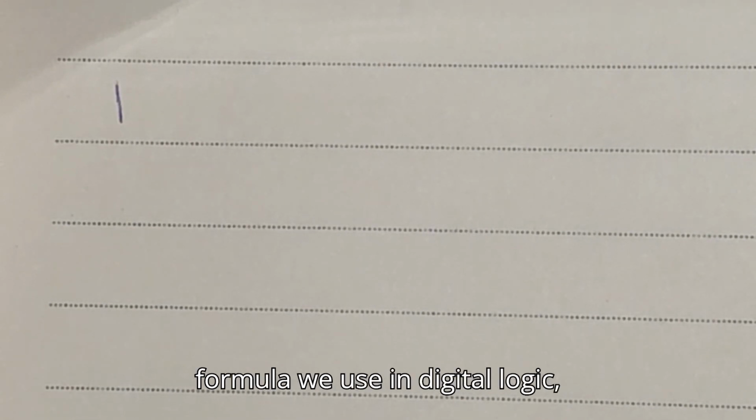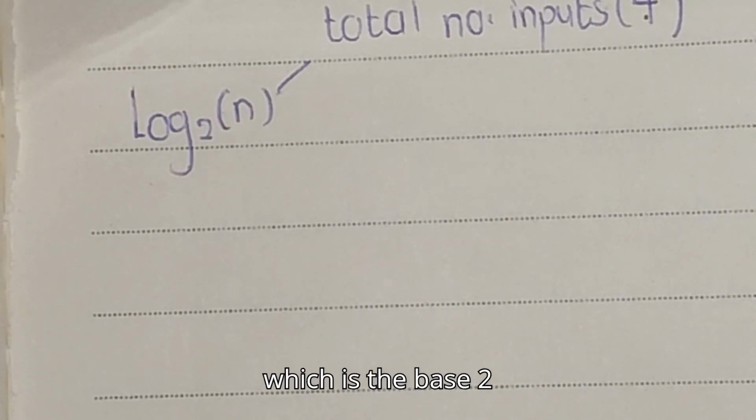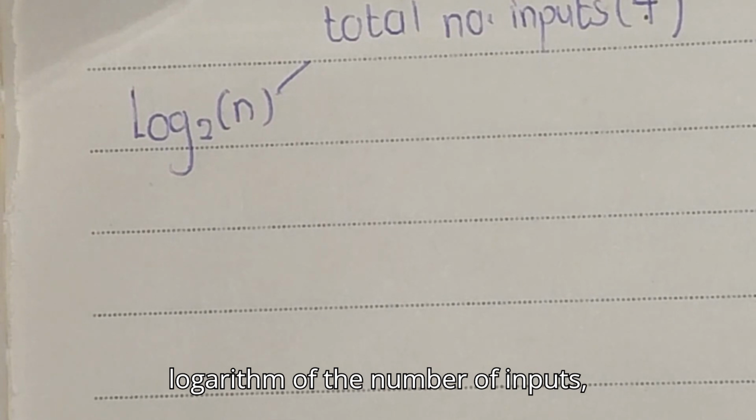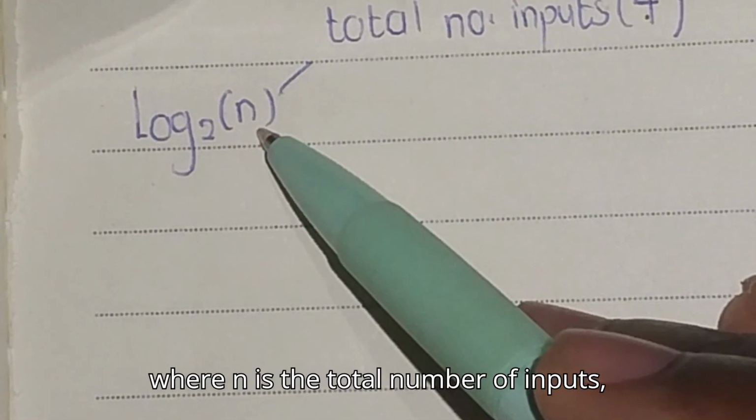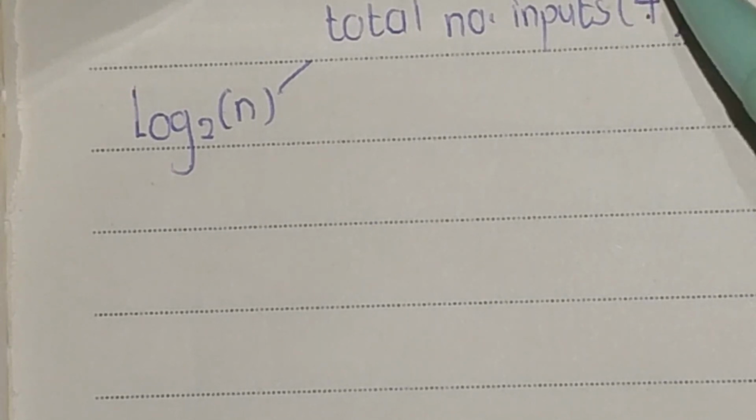To figure out how many select lines or control signals we need, there's a simple formula we use in digital logic, which is the base 2 logarithm of n, where n is the total number of inputs, which is 4.